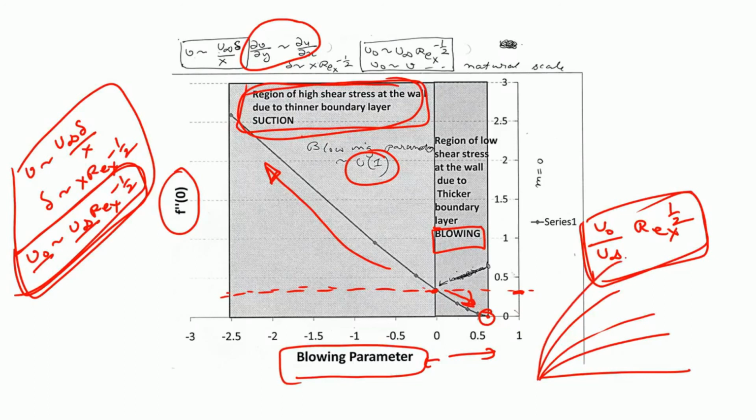After you increase it beyond a certain amount, the flow starts to separate. Say you have increased it to the limit that it has reached this point, so here the flow will actually separate, because the gradient is slowly becoming shallower and shallower. If you look at my hand, it becomes slowly shallower and shallower till at a point it becomes equal to 0, and after that there is what we call a separation.